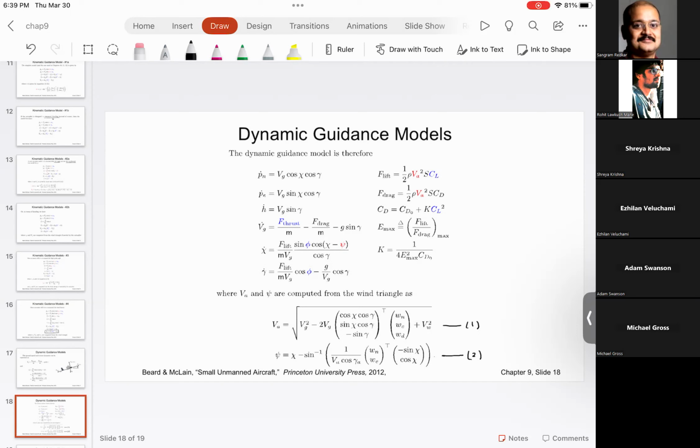Now, please understand, these equations are dependent on time, which means that as time advances, we need to find out the next value of a certain variable. But the next value of that variable is dependent on the measurement that is coming from the sensor, and it is also coming from the previous state that we calculated. And again, you get a very nicely written code or architecture that includes a Kalman filter, discrete time integration, and some type of error checks to make sure that faults don't occur.